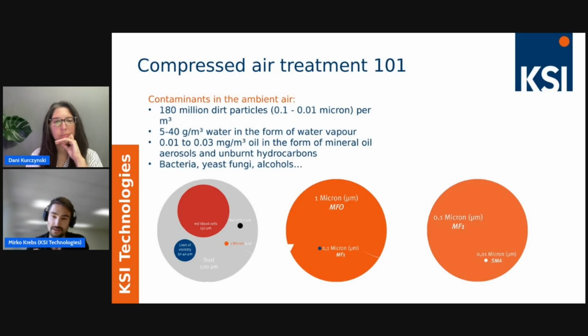So what we would recommend here, Maria, in this case, is a sterile filter that you put at the point of use. A sterile filter has a special filter element that can be sterilized in an autoclave system. So the bacteria, the fungi, the living cells, the living spores that you catch in your filter can be neutralized and washed out of the filter in a recurring fashion. You just take that out, put it in a steam autoclave system once a week, and then you kill off those bacteria, and then it doesn't end up in your system.